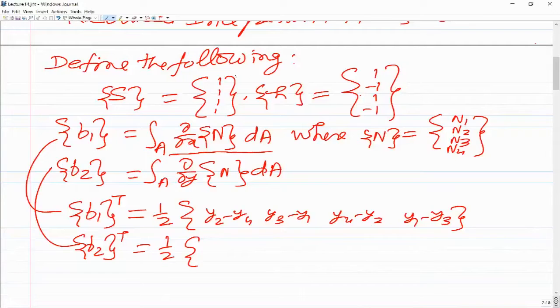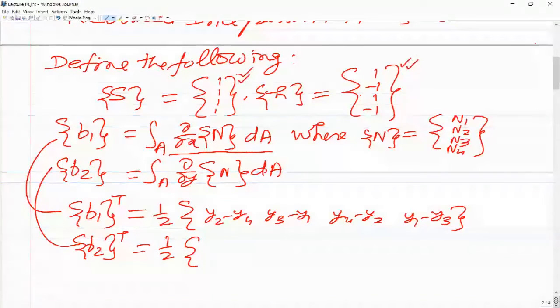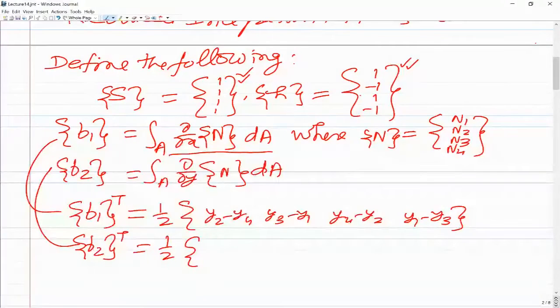So I was saying that it represents the rigid body mode. Let us say w is the same at all the 4 nodes, say unity, so w1, w2, w3, w4 all are unity. So it is representing that. And similarly, the vector h is representing an hourglass mode. If you look at the w values at all four nodes of the element, they would be alternately plus 1, minus 1, plus 1, minus 1. So that is representing an hourglass mode.